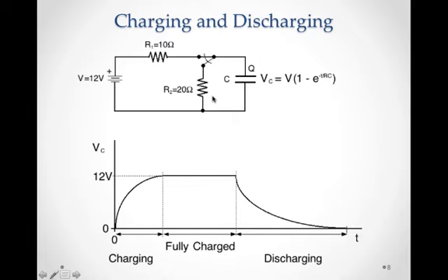And so this is an important feature of capacitors, this idea of charging and discharging them. And in a lot of practical circuits, when you have capacitors in the circuit, they are connected to resistors after the circuit's turned off, like this kind of resistor, to discharge them on purpose so they don't sit around charged up. And those kind of resistors are called bleeder resistors to power down all the capacitors in a circuit.